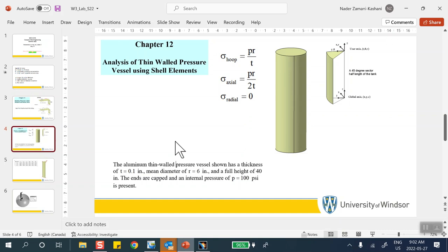If you were standing against the inside of the pressure vessel, and the pressure vessel was pressurized, don't you feel some force on your belly? Because it's pressurized. That's sigma Z. It's not 0. So why do we say for pressure vessels, or thin wall pressure vessels, sigma Z is 0? Look right there. That's what we read in deformable bodies. How do you justify that? How do you justify that in an interview, when the guy would really say, "Do you understand these?" Yes. Can you tell me why is that 0?